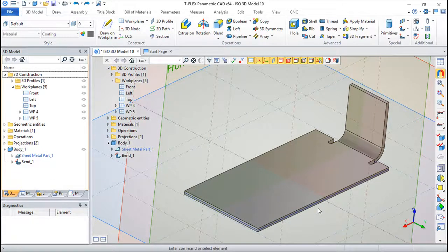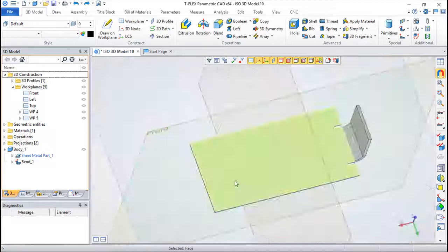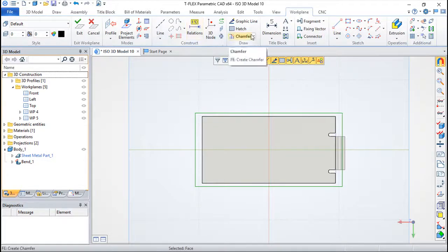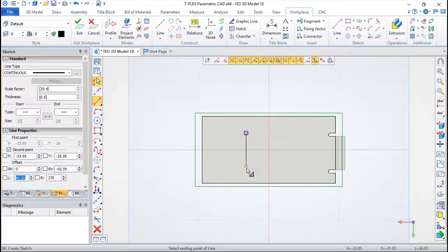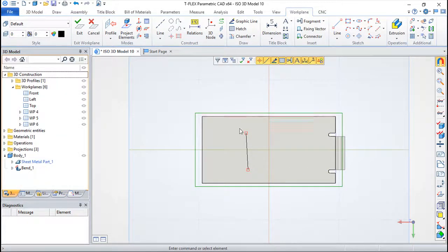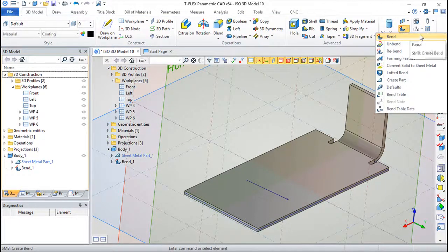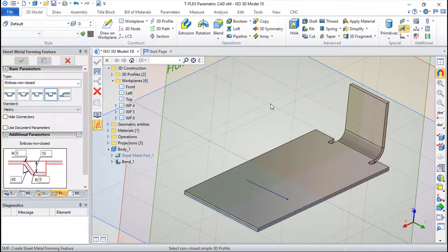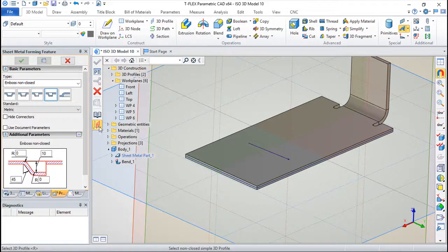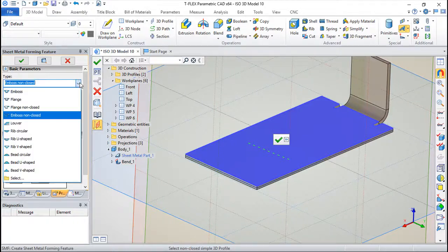And finally, we have also a very interesting feature using the library of features that the program already has. So using the same principle as before, if I do, for example, a line, doesn't matter the shape, and I go to these functions, I have something called the forming feature, and the forming feature allows me to choose a profile and choose a shape from all these ones.